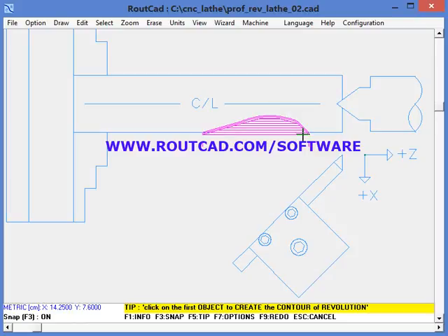You can see the difference between the roughing passes and the finish passes. The roughing passes are just going into the material one by one, 1 millimeter by 1 millimeter, but the finish passes are actually following exactly the contour and going 0.5 millimeter in to give a better finish.